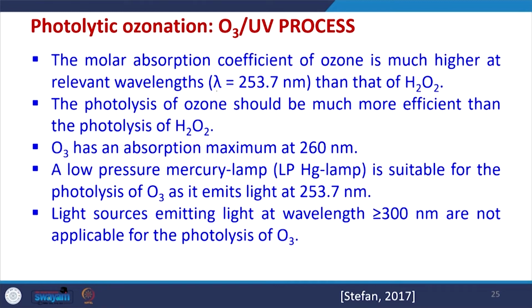For example, at a wavelength of 253.7 nanometers, which is one of the key wavelengths for destruction of pathogens, the molar absorption coefficient of ozone is very high as compared to that of H2O2 itself. So, the photolysis of ozone is much more efficient than photolysis of H2O2 itself.